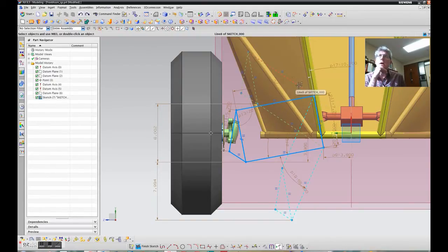So I made this line, I constrained it to be the same length as this line. Likewise, this line is the same length as this line. Again, this line here, line 13, is this link, so I constrained those to be the same length. And all the links to be of the same length as in the neutral position. So if I go in and change something, like the length of this link, originally I had something more like that. It changes the upper and lower positions. Okay.